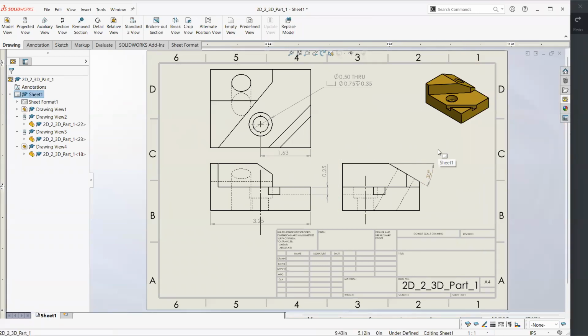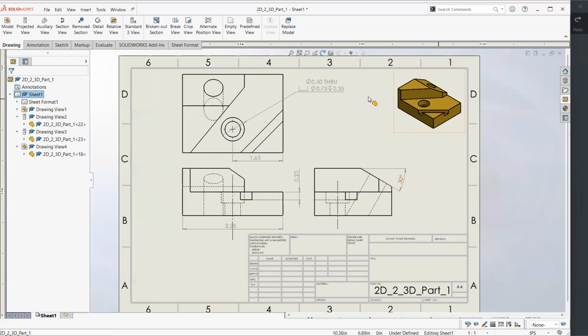However, sometimes those views are not enough to give all the information needed about the part. So as I said, if we would like to give the position of this hole, most commonly in a lot of the standards you should give it in the orthogonal view. Since it is an inclined surface, we could simply go orthogonal, or perpendicular, to that.